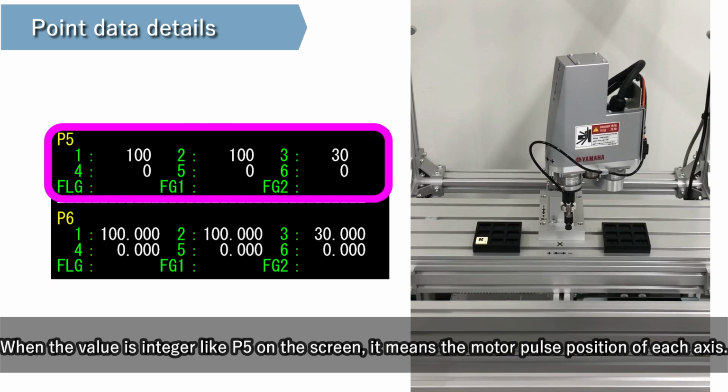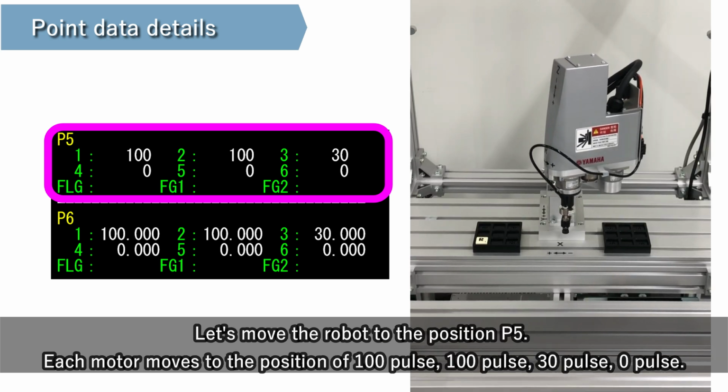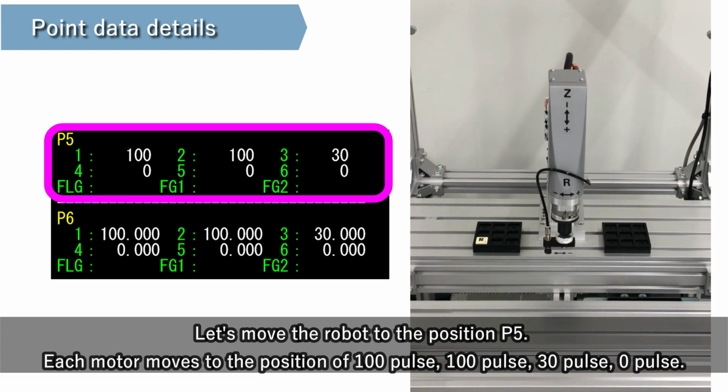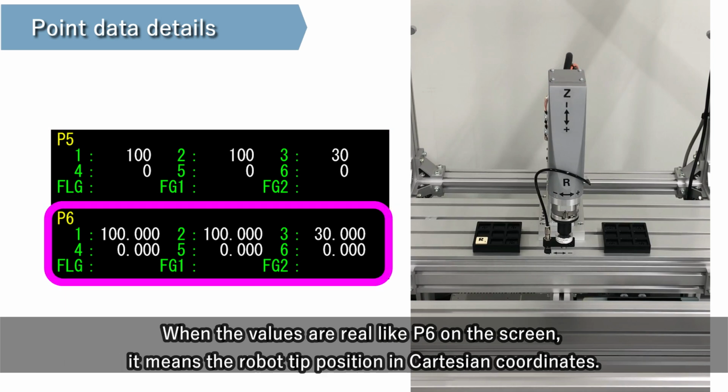When the value is integer like P5 on the screen, it means the motor pulse position of each axis. Let's move the robot to the position P5. Each motor moves to the position of 100 pulse, 100 pulse, 30 pulse, 0 pulse. When the values are real like P6 on the screen, it means the robot tip position in Cartesian coordinates.